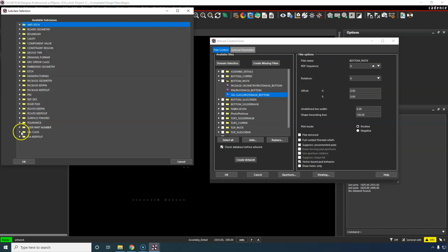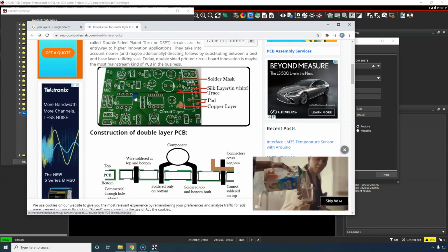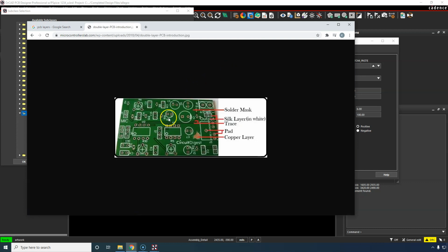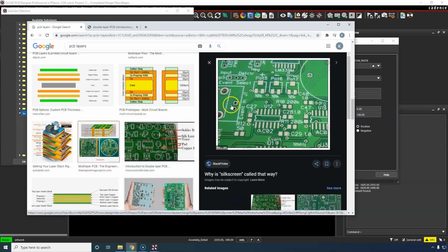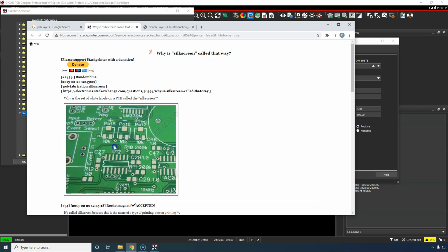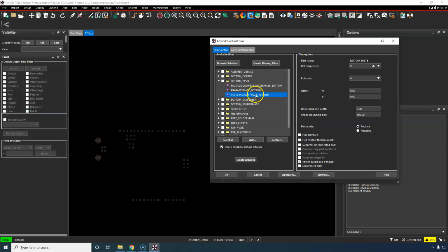Let's look at our vias. Via is vertical interconnect access. It's those little holes that you see on the PCB. Let me give you a good example. It's a terrible picture. Anyway, see this via right here? There's some exposed copper on here. Now, I don't know why you would even need paste mask on a via. Actually, I would take that out. But if you want to take something out, you can right click, cut it. It disappears.